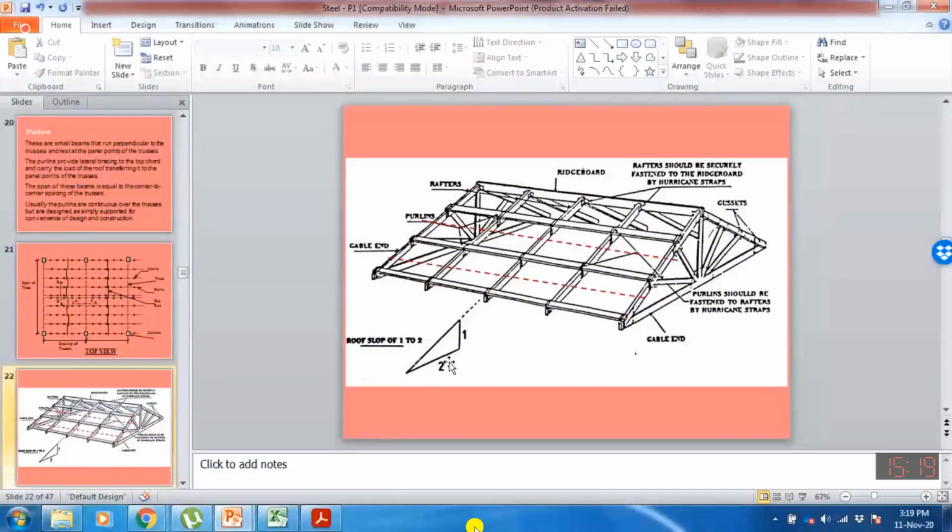Actually, the F force is provided in direction 2. The charts which are given on page numbers 79 and 78 provide the force in two directions. But actually the sag rods are provided inclined. So this inclined direction, you can assume, is the R value. If you know this F value in direction 2, you know the theta. So F over R is equal to cos theta.